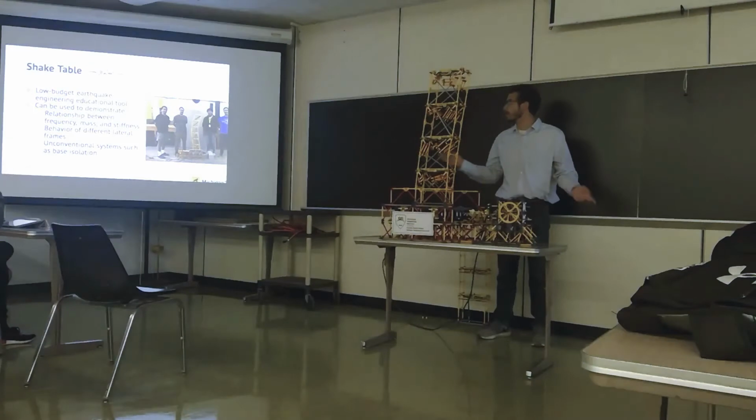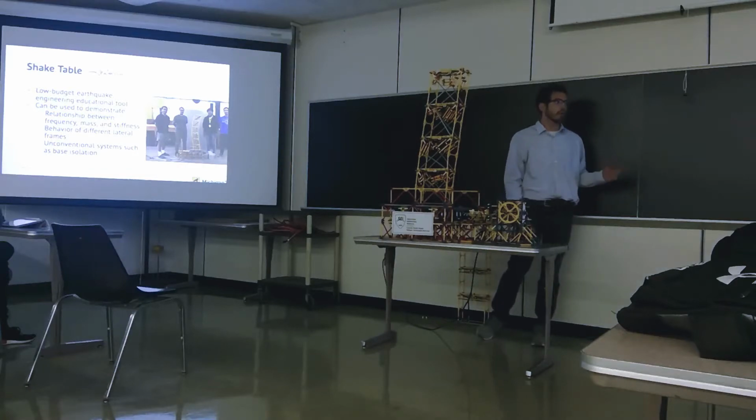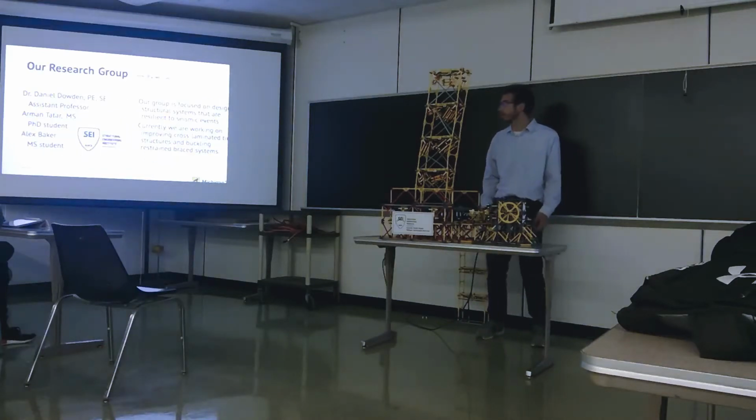So just a brief thing about the shake table. Again, we developed it as a low budget earthquake engineering educational tool, since shake tables that you can buy are generally going to be thousands of dollars. We're using it to demonstrate relationships between frequency, mass, and stiffness, like I showed, and the behavior of different lateral frames. I also have some systems, so you can show base isolation, rocking frames, non-conventional systems.